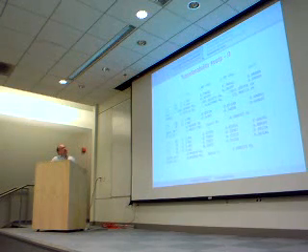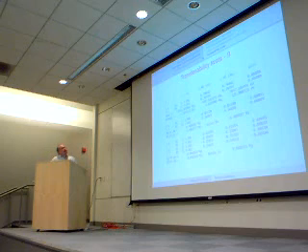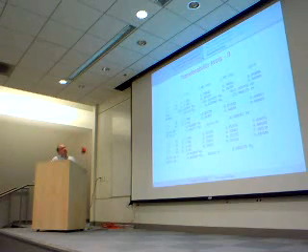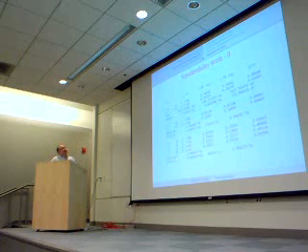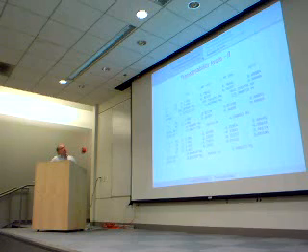You see on the fitting configuration, the 3s2, 3p2, it prints the all-electron eigenvalue, the pseudo eigenvalue, and their difference. So from here we see how good the pseudopotential is, because it compares the pseudo and the all-electron eigenvalues. On the configuration that has been used for the fit, there is clearly no difference.